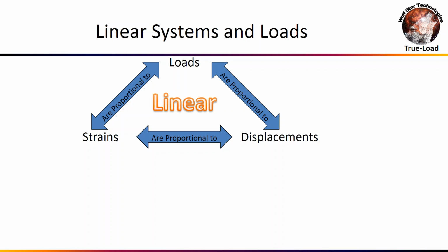So the loading can be as nonlinear as anything. The loading can be ramp loading, sinusoidal loading, impact loading. That's fine. I just need the strain response at the strain gauges to remain proportional and linear. That's the only restriction here.